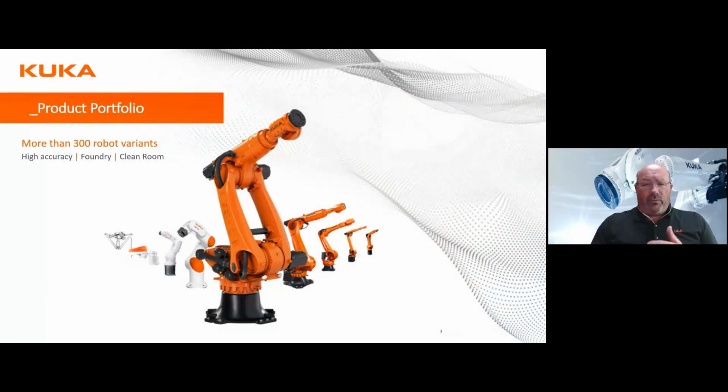So when developing robotic solutions for machine tending, several factors need to be considered when selecting the proper arm. You can see here KUKA has a wide variety of robots in our portfolio. But when you're selecting the right robot, one of the factors is the robot reach. Robot reach is a measurement of distance given, in the metric system, and it can be shown in millimeters, like 600 or 760 millimeters, or conversely in fractions of a meter, like 1.6 or 2.1 meters, and so forth.